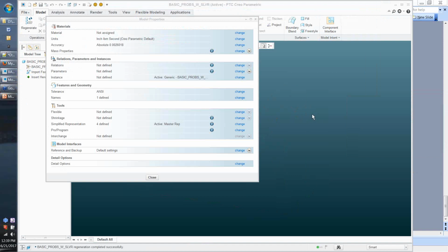If I can't get a repair to fly in that case, it's very typical that one of those two surfaces is a bad operator on the face of it. It's just a bad surface. More often than not, you could be better off, if you have to, using it as a template and just recreating it and collapsing it in, rather than continuing to fight something that won't repair with typical zip gap techniques, because that is very robust. So typically I might use match in a case here and there, but I will use the typical repair functionalities that I showed today more than anything else.